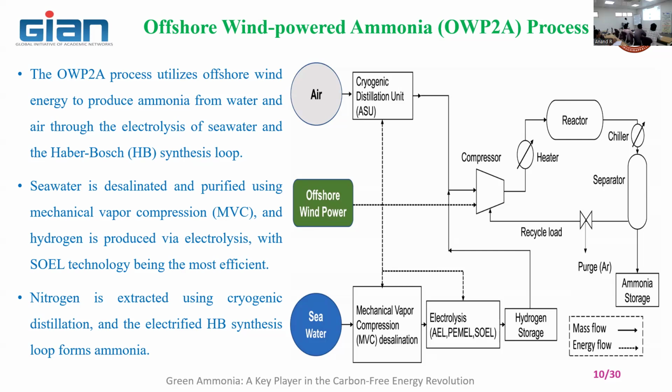ammonia. So in order to raise the temperature, you are using a heater. The heater may use some renewable fuel to produce heat, or electrical, microwave or plasma technology can be brought in here to raise the temperature of the nitrogen and hydrogen mixture coming out of the compressor, heating it to 400 to 500 degrees centigrade. The pressure increases due to the compressor and the temperature increases from the heater, and then you maintain these conditions in the reactor.